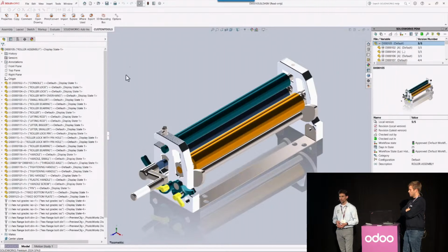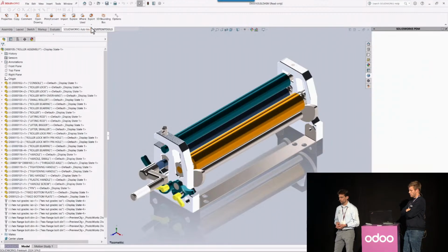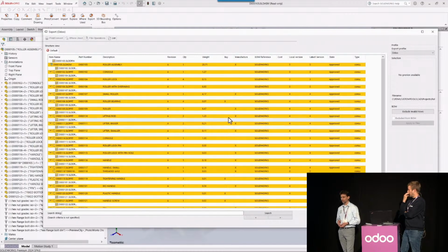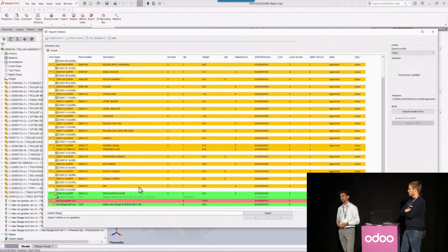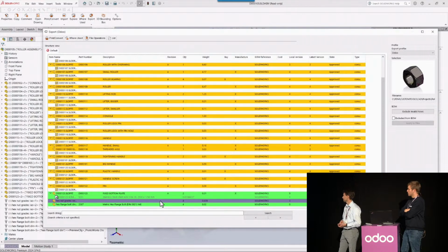We don't need to do that now for the bolt, but obviously we would then repeat the same procedure. But if there is something that is missing, you can always just exclude the items from BOM as well. So sometimes there is something that you don't even want to export, so you can just click the row and choose to exclude that BOM line from your BOM.